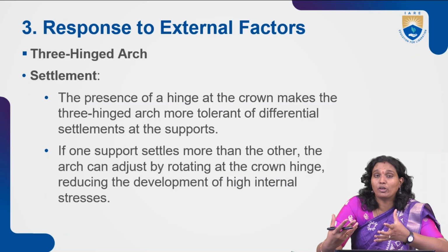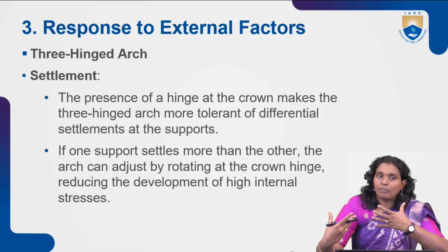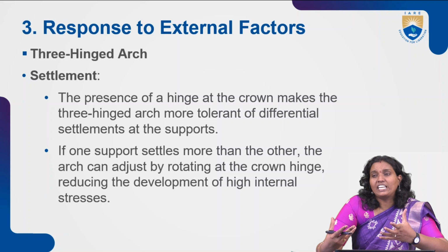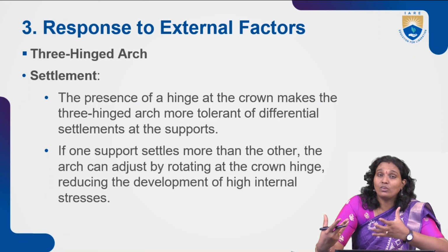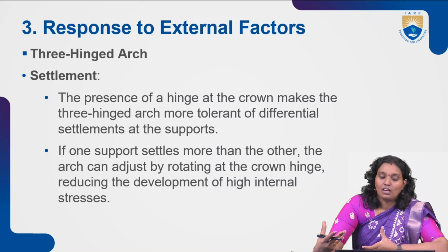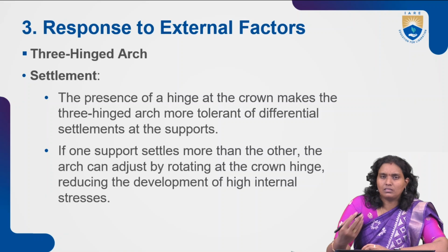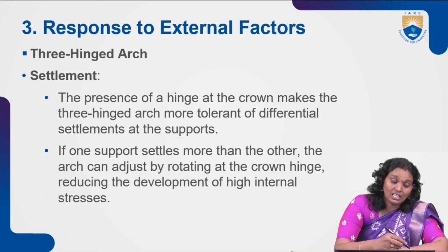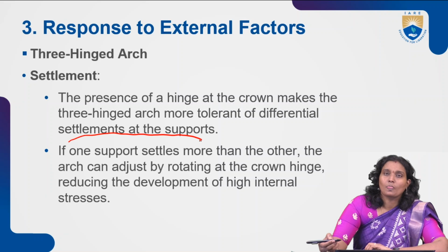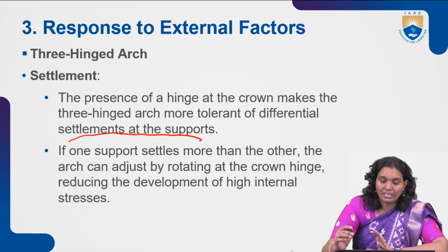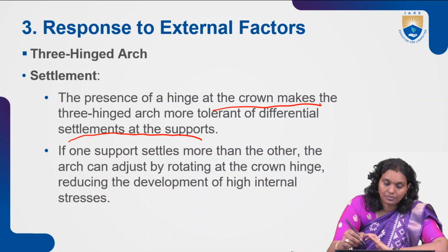So how do we get this flexibility? The additional hinge at the crown gives all these tolerances, and because of this we are able to tolerate the settlements at the supports. So this is the presence of the hinged crown.